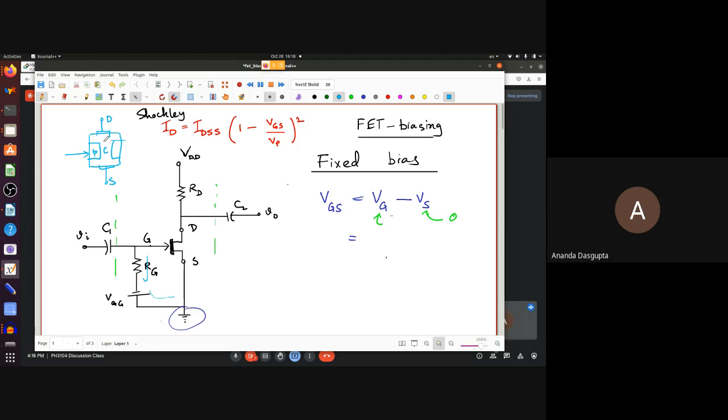By the way, the gate is P-type, the channel is N-type for us. And so remember, this is almost like a diode, this part. And that is exactly what this arrow is supposed to remind you of. There's a PN diode, where the P side is the gate and the N side is the channel. So how much current will flow in this situation? No current. Minority carrier currents can only flow, which is very low. So no current is not exactly right, but almost no current.